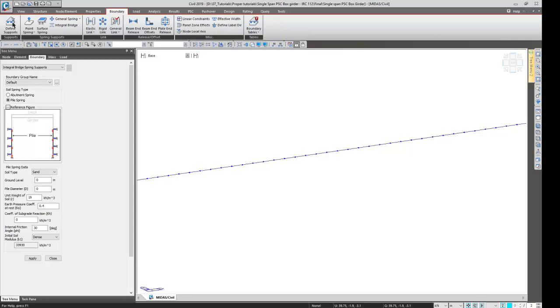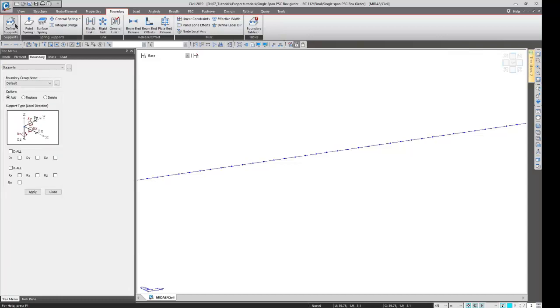So yeah, again, we know the advantage of using spring supports over fixed supports, right? As we know, the more flexible your substructure or any structure is, the lesser the force it will take. So by providing spring stiffness or spring supports, we are making the structure flexible, thereby reducing the force transfer in the structure. That's why we prefer soil springs over fixed supports to model our soil.